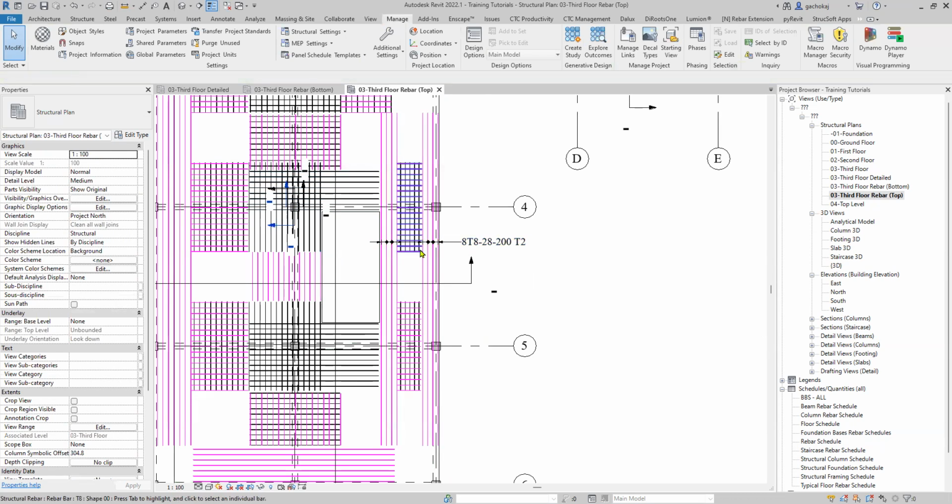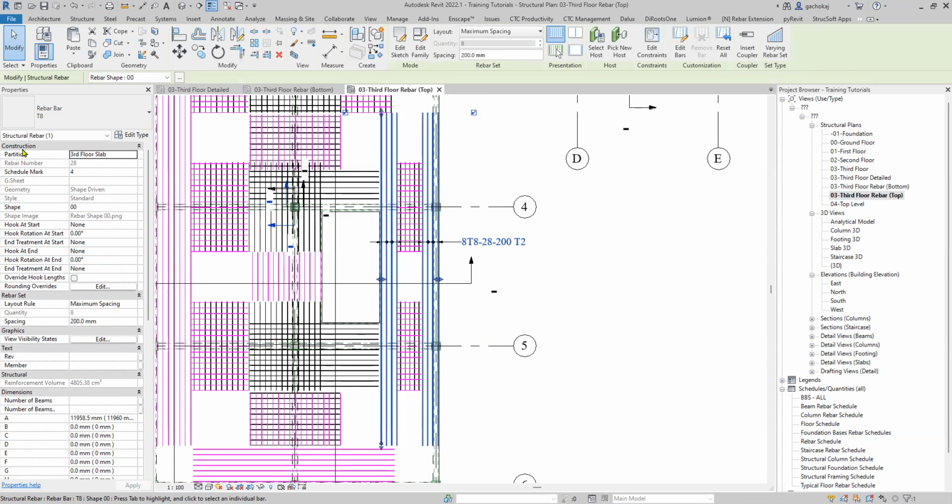So I mentioned partition in some of the rebar videos. So always make sure that anytime you reinforce in Revit, you put in a partition in your reinforcement. It's quite helpful. I'll show you why a bit later on in this video. It's quite helpful in organizing your reinforcement, either in your schedule or when you're doing your reinforcement settings.